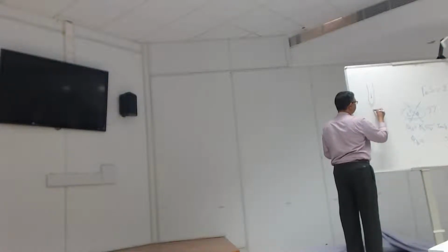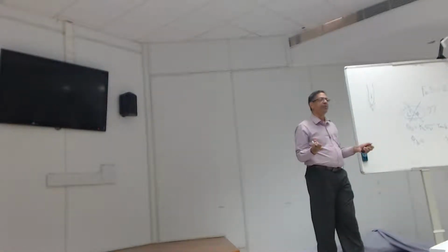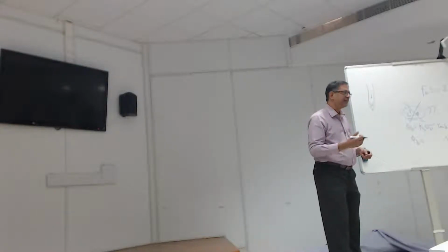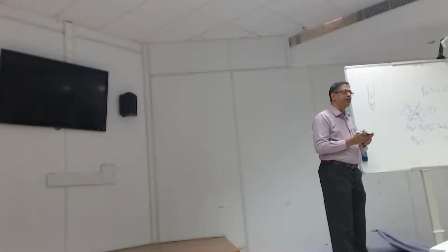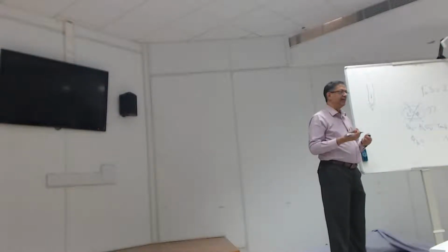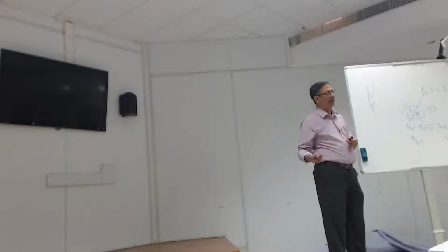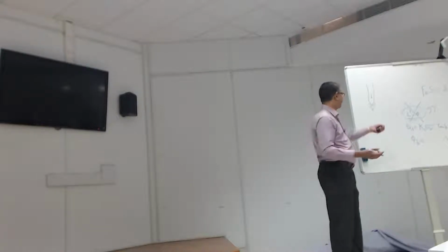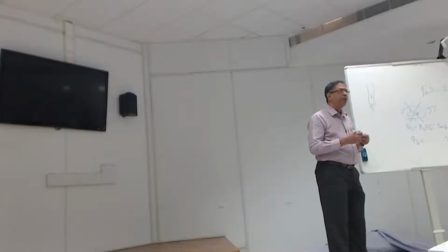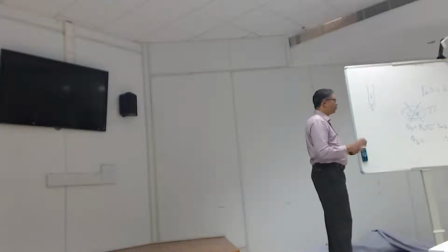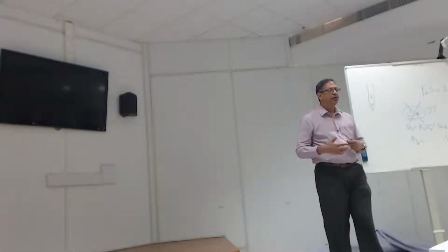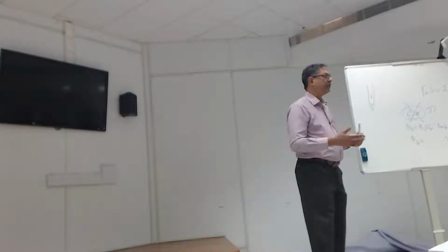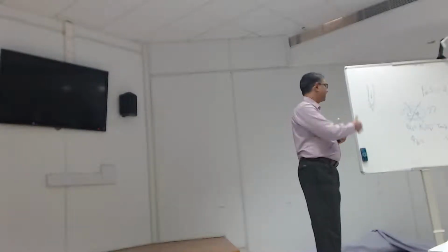And as the pile advances, you have to go away from the pile as well. In doing that, you tend to undergo shear deformation, and whenever you shear soil, you will undergo a volume change, unless you are at critical state, which is unlikely, because you are at a natural state to start. So you should always expect the soil at the base to be dilated, because it has to shear as the pile comes in.